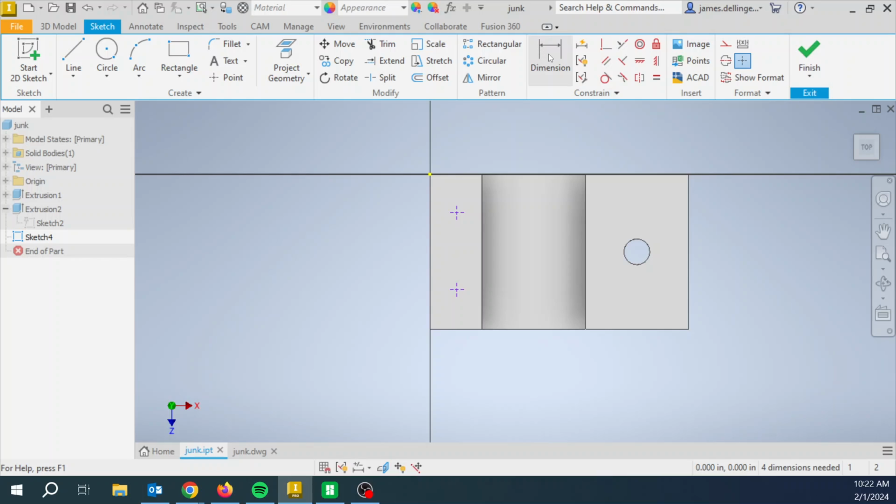And then I'm going to say, hey, with the dimension, I'm going to come from here to here. We're going to say, let's see what 1 inch, nope, that's too much. Let's do 0.75. Let's do this one, 0.75, same thing, right? I'm going to say those are always equal, so that's going to be equal to that, just because I want them to always move together. So I'm going to make that one a function, right?